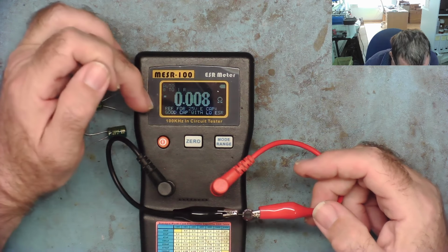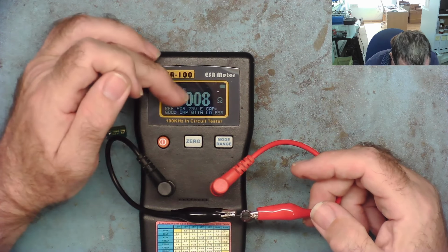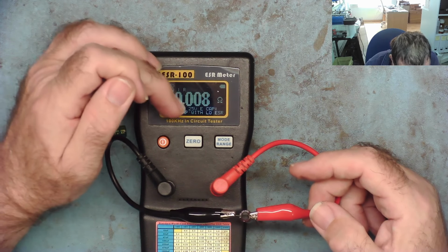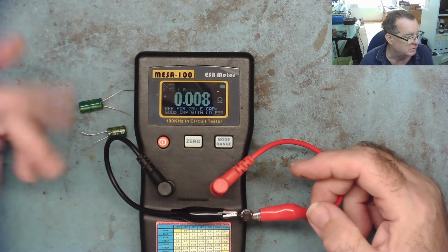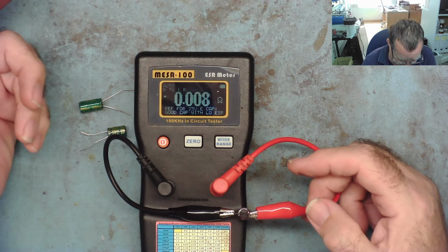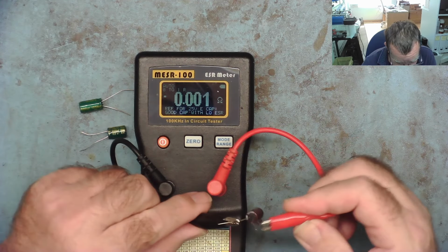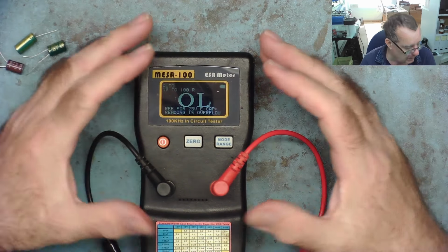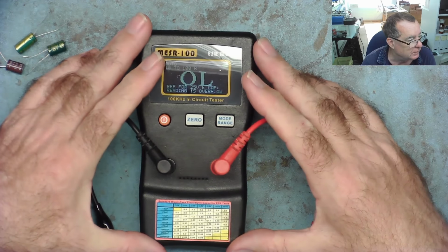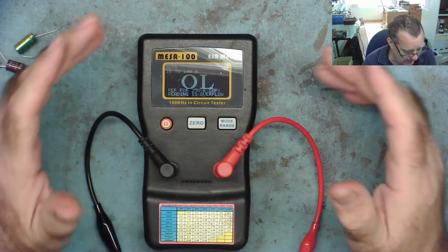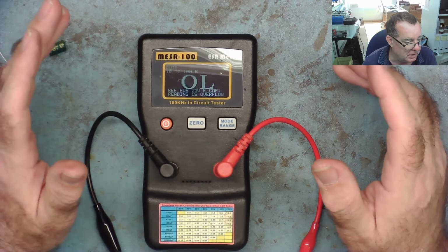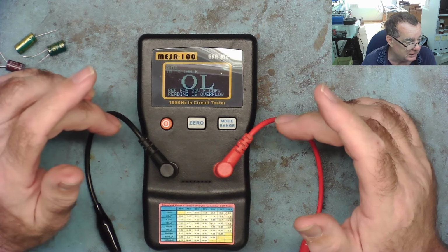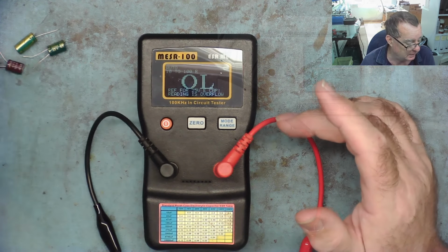Now it's telling us here that for capacitors 25 volt, yeah, the capacitors with low ESR. So it's saying if it's a 25 volt capacitor or lower, it's a low ESR. Okay. So that's what the ESR meter does. Now, how does it do it? Well, as I explained earlier, it does it by passing an AC signal through the capacitor, and we can actually see that on an oscilloscope.